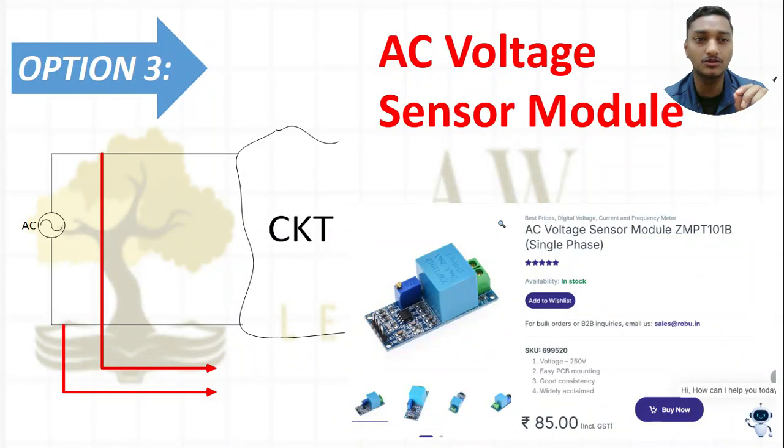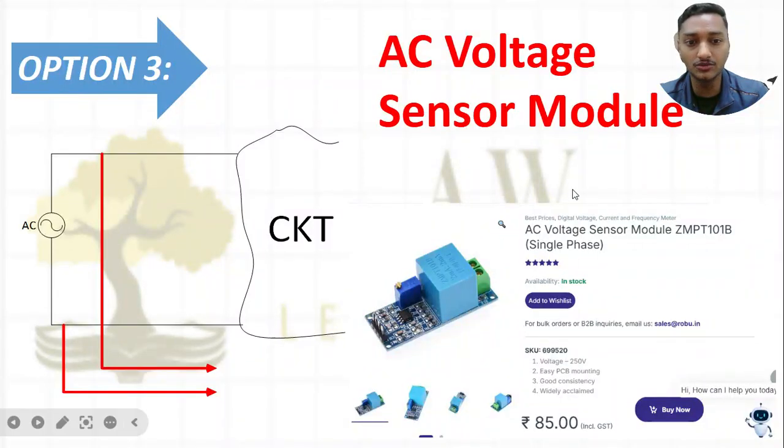So your mean or average value is always 2.5. This particular module you can use for AC as well as DC, but it is very low cost and maybe not that reliable, I guess. That is why people use the OPA based ICs or some isolated options, or I will tell you some more options that are there. So these options are generally used.